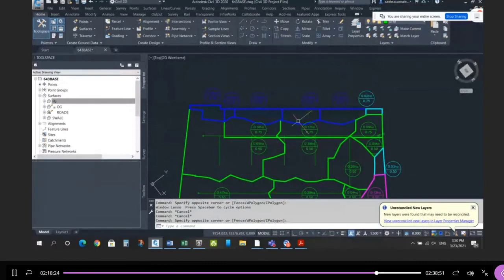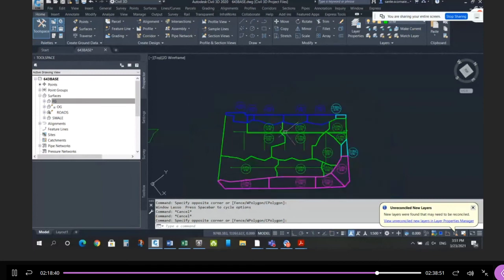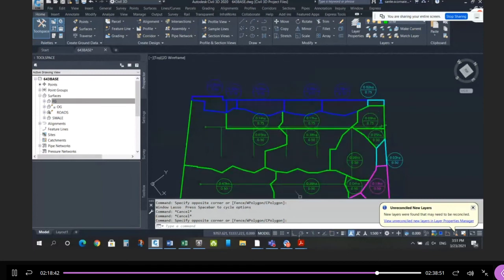Well, yeah, the geometry works, right? There's low points and catch basins in places that allow that flow. Then I've got a split point, kind of in the middle of all the lots, that will take the drainage internally, and then those backyards are going to go to the other part of the subdivision. So it's a theoretical kind of want at this stage, but then you prove it with your calculation, right?